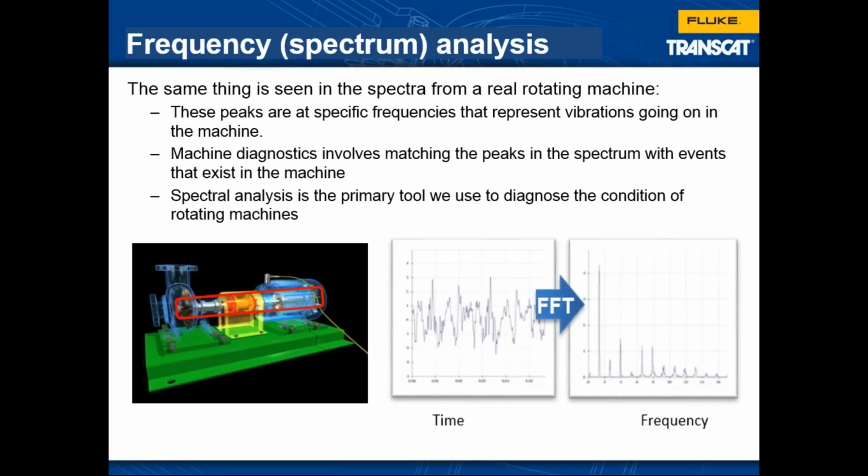Now, what we do in vibration analysis is take all of these vibration peaks and identify them. So here you can see that all of the jumbled up vibration, we separate each of those individual vibration sine waves into a peak. And that's why a lot of the time we look for these peaks. Each one of these peaks can be identified as a component inside the machine.